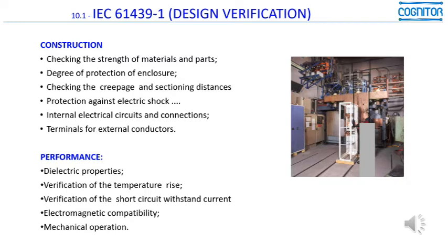And many times when you read the numbers, if you follow the concepts of design which exist in the medium voltage IEC standards, you see that the limits which were reached in the test are higher than would be permissible for a medium voltage switchgear.